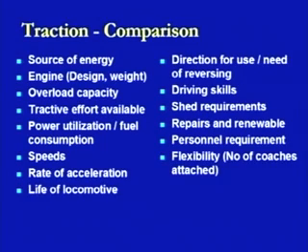The flexibility here is being defined in terms of the number of coaches which can be attached to the same locomotive. Today we are running 18 to 24 coaches with one locomotive. If there is an emergency and there is a need of incorporating some more coaches between two points, that is the origin and destination, that flexibility is there more in the case of electrified locomotives as compared to the diesel locomotives. This is because there is a possibility of installing some more power units on the same locomotive, as compared to the diesel locomotive, where another locomotive is to be used if more coaches are being attached.